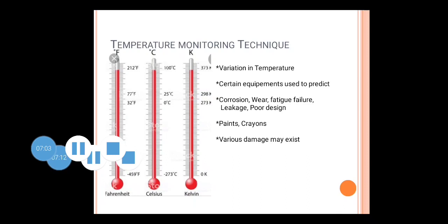Like bearing damage, effectiveness of the lubricant, deposit of foreign materials, damage of insulating materials. Surface damage to rolling bearings on account of rubbing causes heat generation. This heat generation increases the temperature of the bearings. An excessive rise in the temperature of the surface may cause wear and tear, so it may lead to cracks. Henceforth temperature monitoring is very much important.